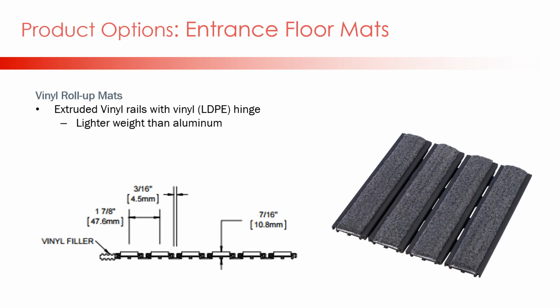Vinyl roll-up mats are 3/8 inch deep and are ADA compliant when combined with a beveled frame. These are suitable for indoor applications only due to the expansion and contraction of vinyl in extreme temperatures. There are a wide variety of tread inserts available for scraping and absorbing.